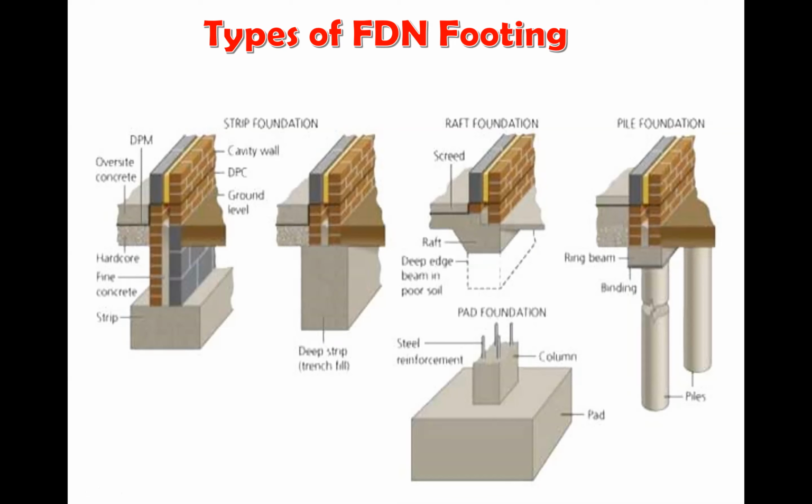If you don't even have walls yet, let's say it's a frame structure, you go from the roof to the beam, down through the columns, then into the floor, then into the beams, then into the columns, all the way down to the foundation footing. So the walls that are built in between those columns are non-load bearing walls. They would have their own foundation just to carry their own load. But these are the pad foundations for those isolated column structures.